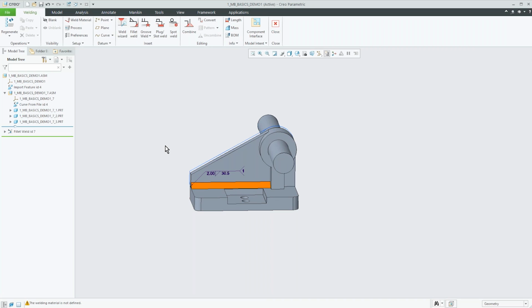And then Steven is asking, can you easily break up a STEP import that is one body into an assembly? Good question, because if the STEP comes in as one, you can cut it up as I did with my third example. But to get it into an assembly, you could STEP it out and STEP it back in.